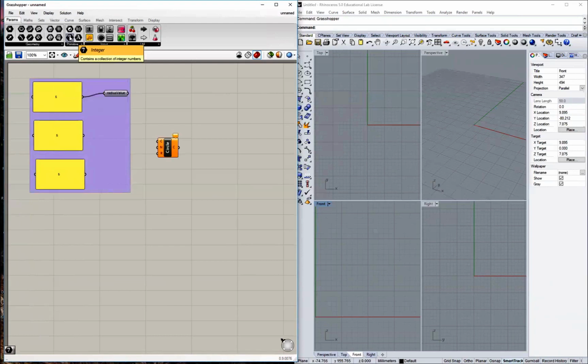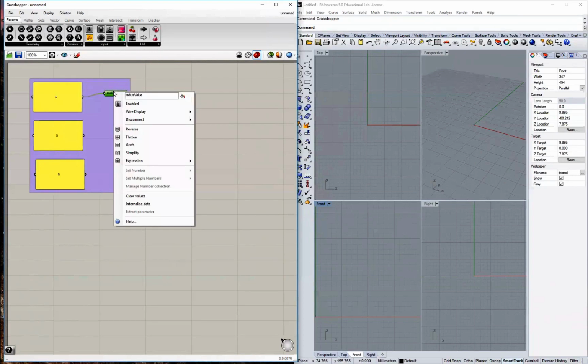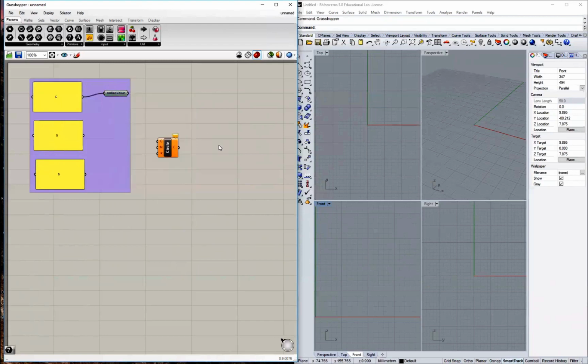The other thing you can do is, if you have a node and you know that node is out of date, you can go through and right-click on a node, and you can say that you want to recompute that node, just generally by right-clicking on it. Let's see if this one will let me do it over here. Looks like I don't have enough wired up right now to make that happen, but we'll show you that later. So again, you can just recompute to force things to go through and reevaluate at the time.